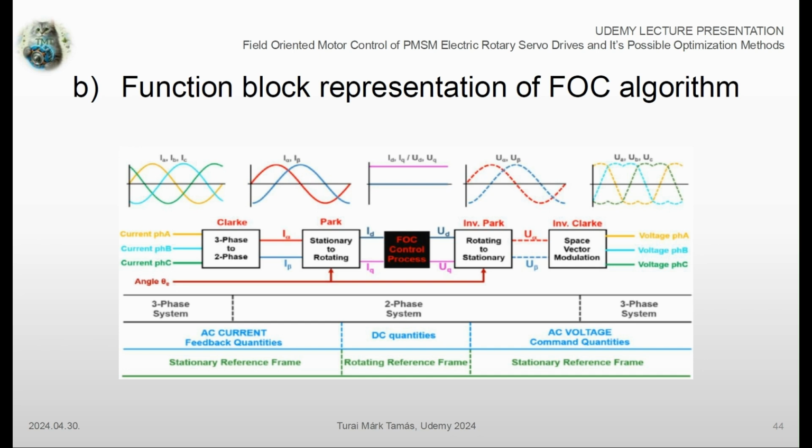After we have utilized the controlled voltages in the XY plane, we shall transform these physical quantities further to the three-phase coordinate system. The so-called SVPWM algorithm is used for the most efficient utilization of the available DC bus voltage to the PMSM motor phases. The function software that we are going to develop together is going to calculate the appropriate phase voltages that the so-called BSW or base software shall transfer to effective IGBT or MOSFET switching signals.